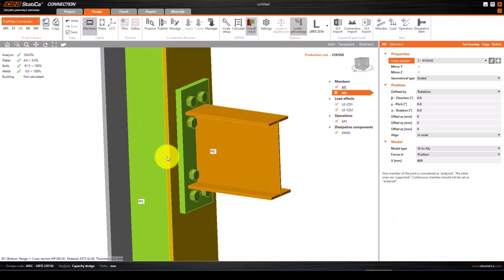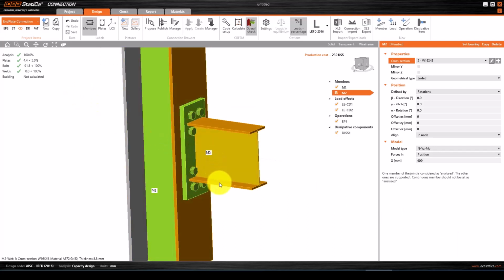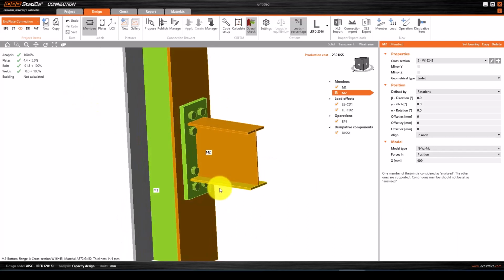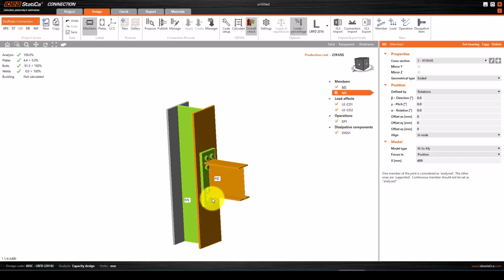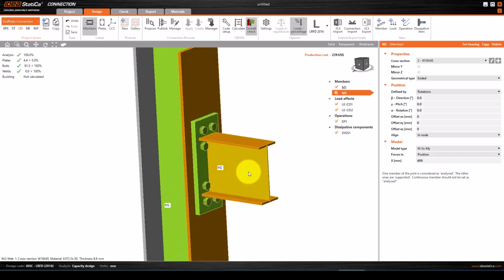Now the analysis is completed, and we got a very nice result. Very nice result, but here are two important things. One is the color, which seems to be a very economical design. This green is a very optimal design, and that one is a very over-strained design. It's not economical, this line, so that means some instabilities exist. For this we can add some extra stiffener in the column, that will be better. By adding that stiffener, the cost of the connection design will not increase too much.